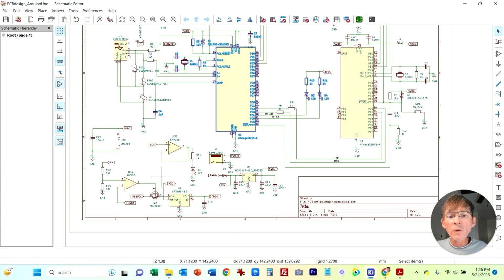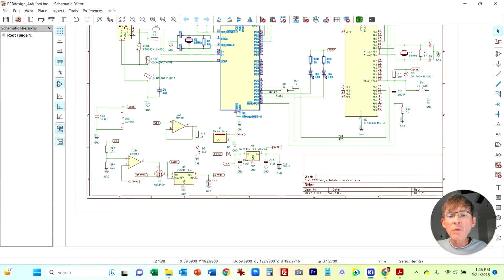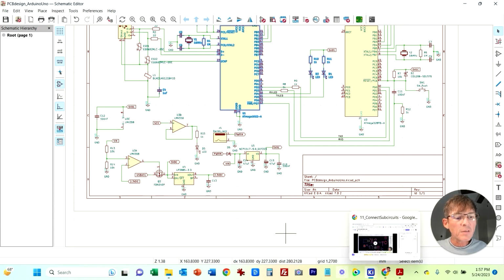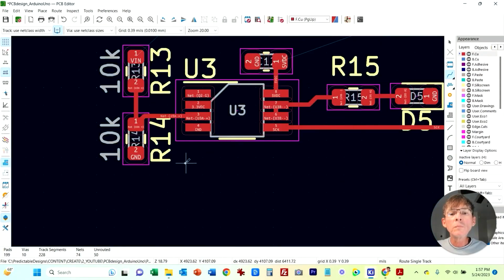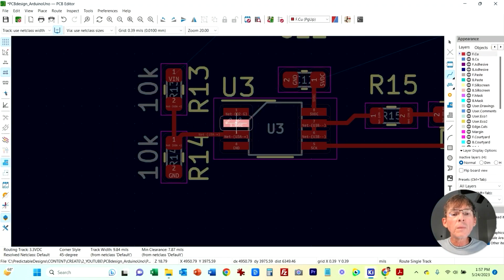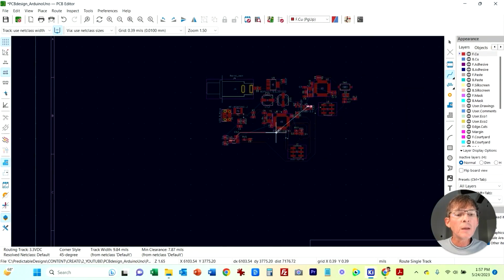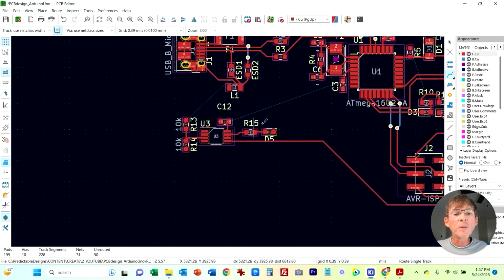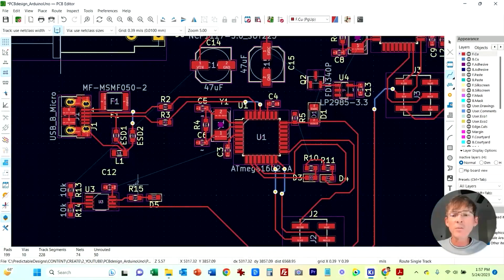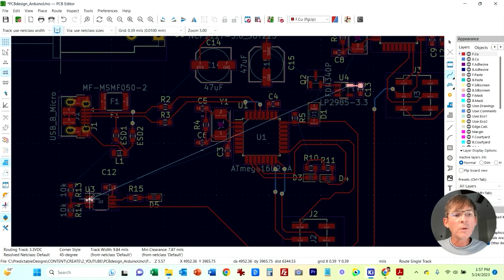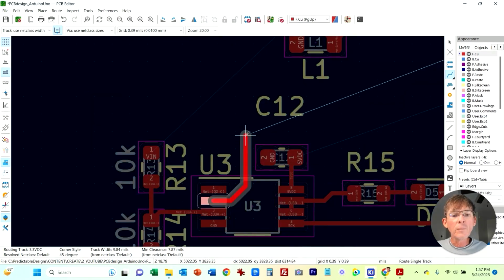That's here. We have USB VCC. That's separate from the 3.3 volt. Let's see. That's a power, so I'm going to do the 3.3 volt. Well, there's really nothing else that goes to 3.3, so I might as well go ahead and do that now.